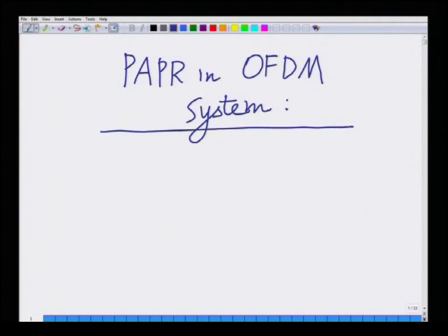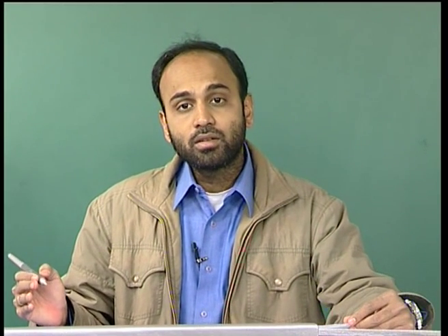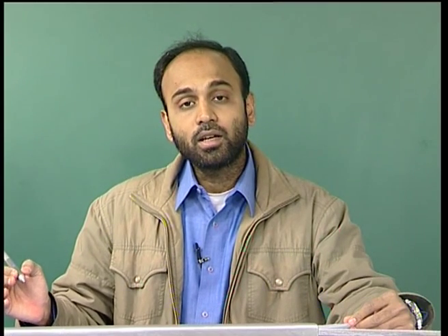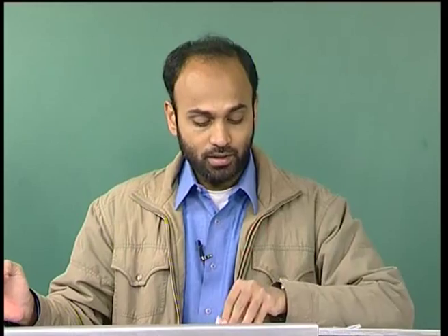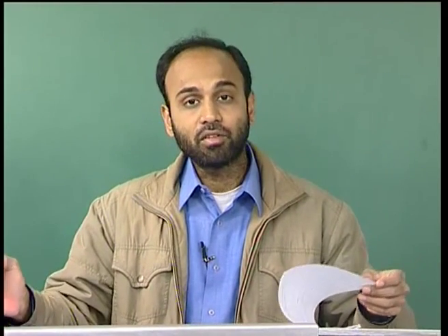Now, in OFDM, remember, we are not transmitting the symbols as is, but we are loading the symbols onto the subcarriers, and then we are taking the IFFT of these symbols before transmitting these symbols. So, we are considering the IFFT of the symbols.